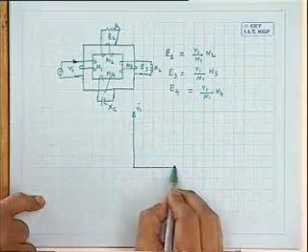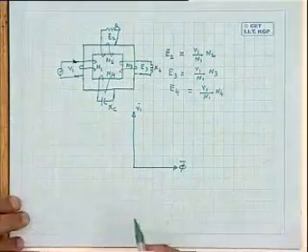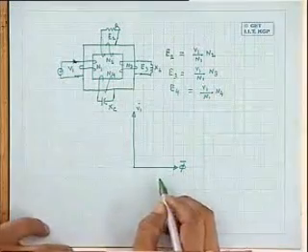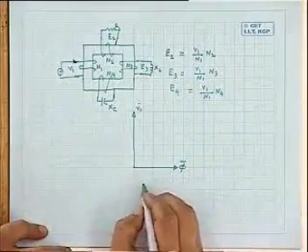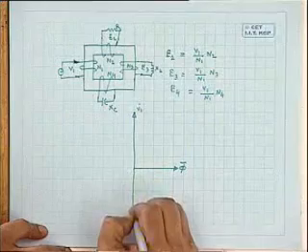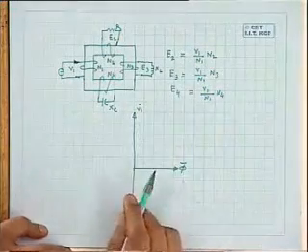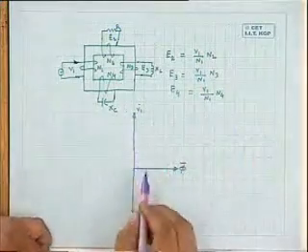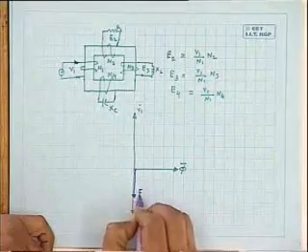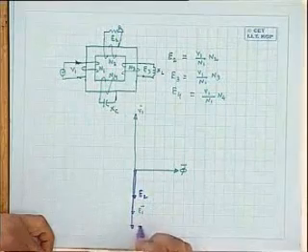There is obviously flux induced in the transformer because of very negligible magnetizing current, which I am not showing because it is so small, Im, in an ideal transformer. Then there will be induced voltage in all the windings, where E1 will be the same as V1, and depending upon the ratios, you will get the voltage induced in E2 and suppose in E3 here.